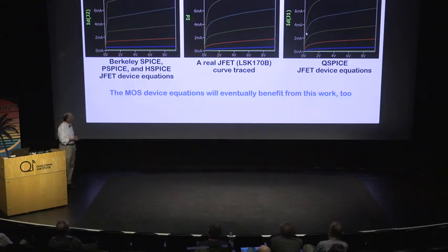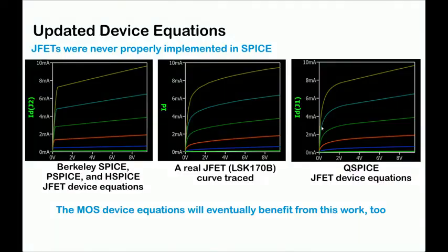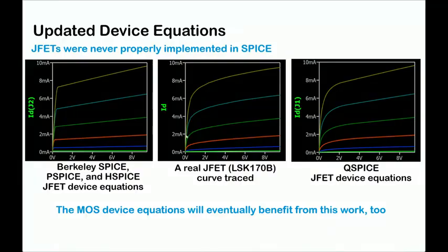And the other thing is that you really need to know the current. So the current measuring was done with a TIA circuit. It's basically done with an electrometer type circuit. So you'd know the current. You didn't have to worry about four-wire techniques. I could just casually connect alligator clips to my device and get these curves. So that's how I fell in love with KiCad, is making the board for this thing.